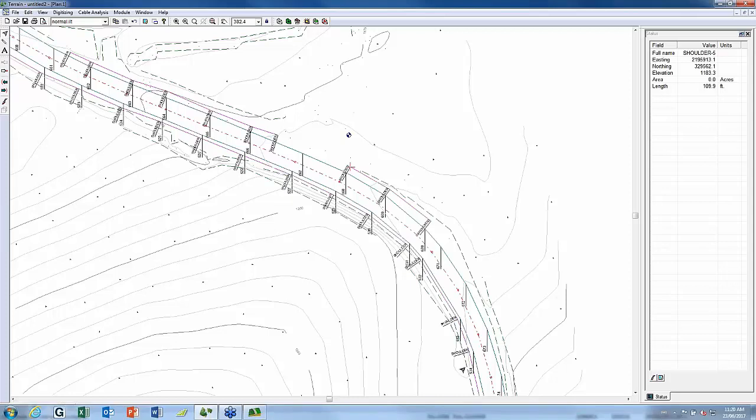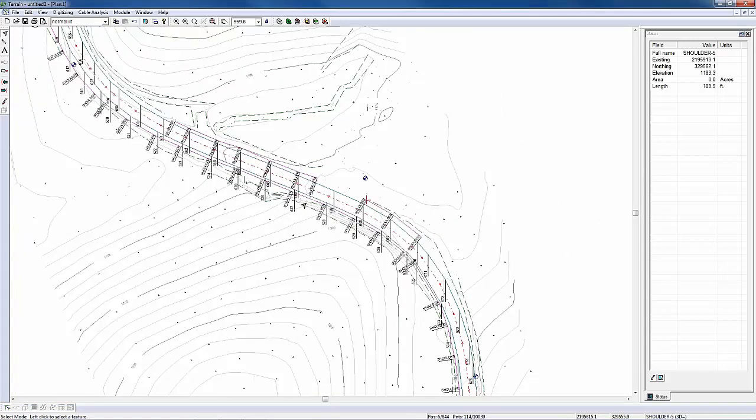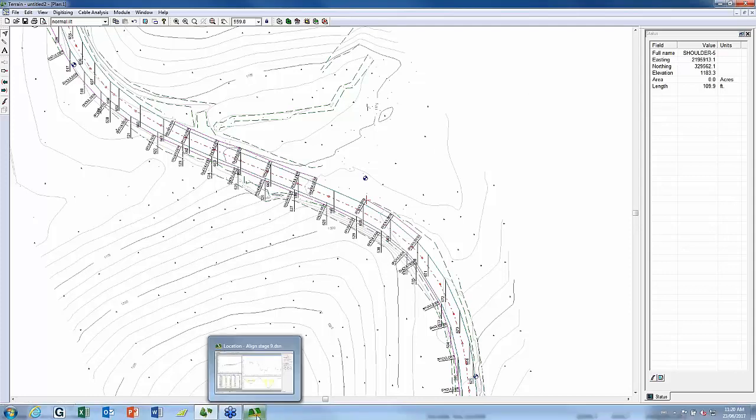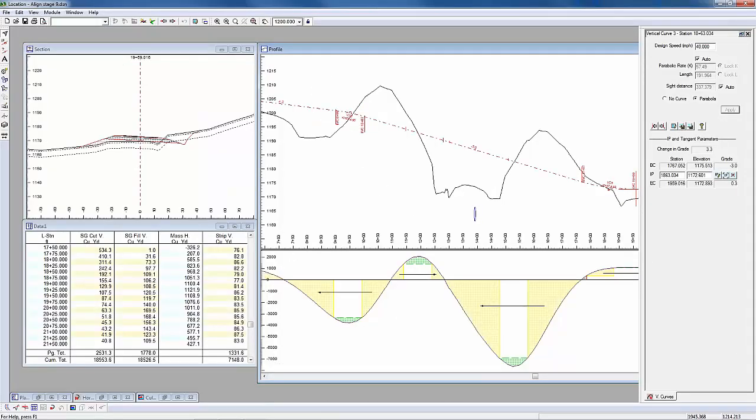All right, now that you guys have an idea of how to import total station files, I'm going to show you at the other end how to export to total station and to LandXML, so that you can upload to your total station unit, and LandXML so that you can upload to a machine grader. First of all, I'll do the total station one.